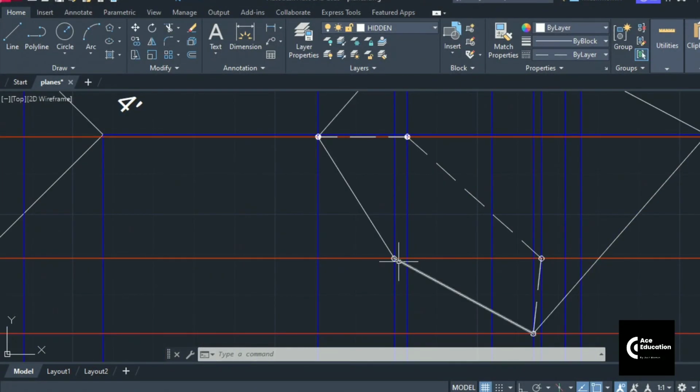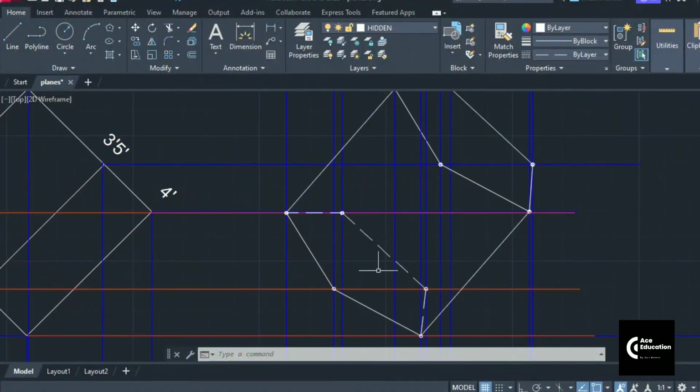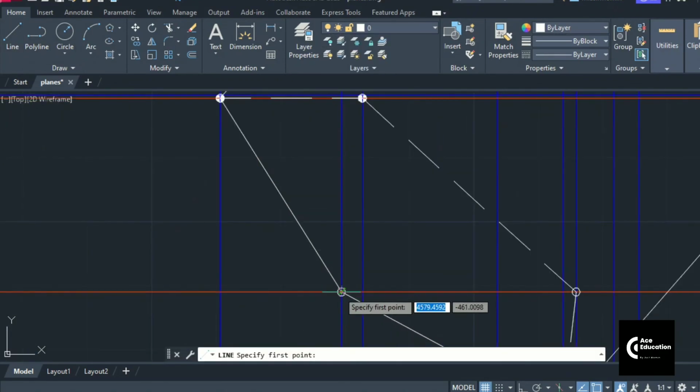So this is a corner point of the base which is nearer to the observer, as the line started from this point can be seen directly. Whereas these are the 2 corner points which are beyond the surface, because of which the lines started from these points are not visible. So here you can see the vertical edge between these 2 points would be directly visible. Go to the outline and draw a line between these 2 points.